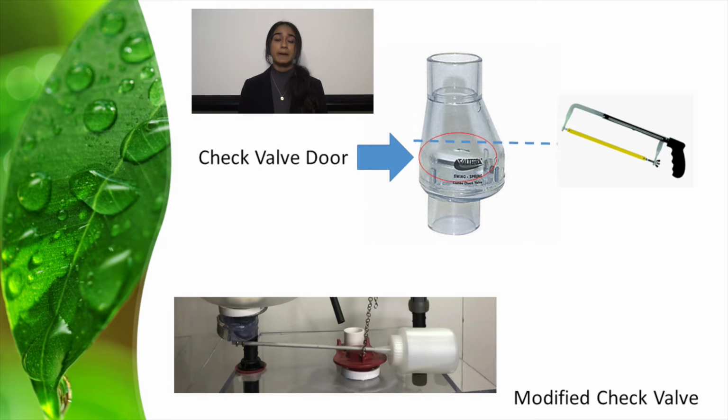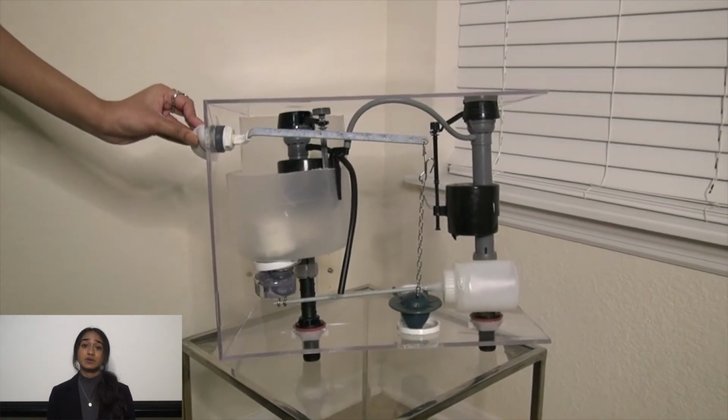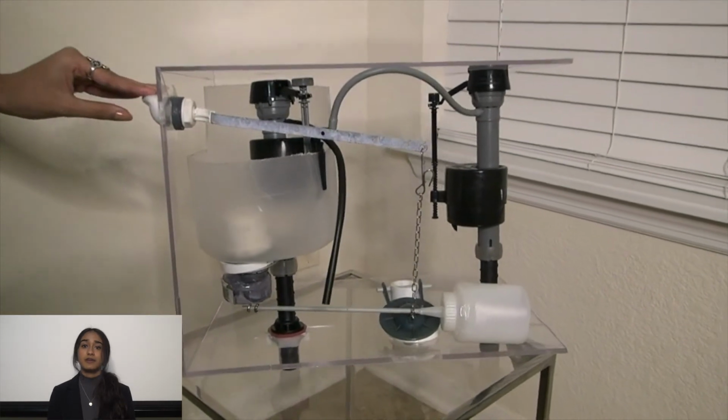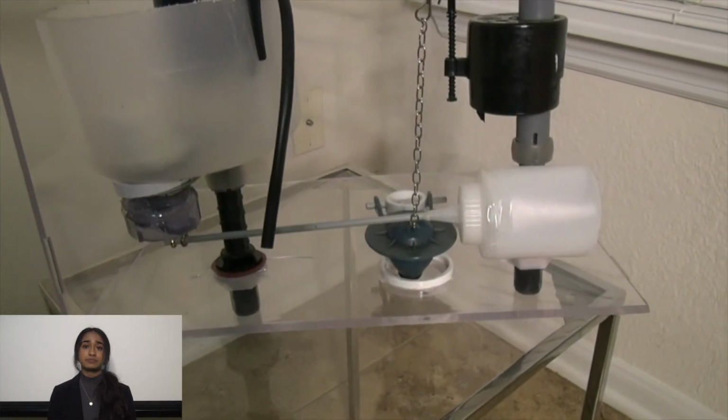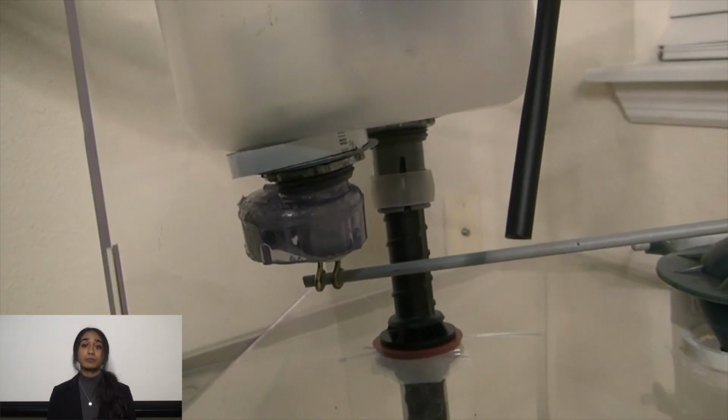When there is a minimum amount of water in the main tank, the valve will be kept closed, similar to the traditional ball float principle. One of the accidental discoveries during my research ensured 100% freshwater savings. During each flush, when this lever is pushed, this rod connected to this float is mechanically lifted regardless of the water level in the main tank. When the rod is lifted, the drain hole is closed, and the freshwater valve remains closed. This achieves 100% freshwater savings.